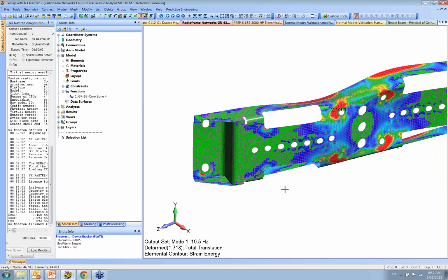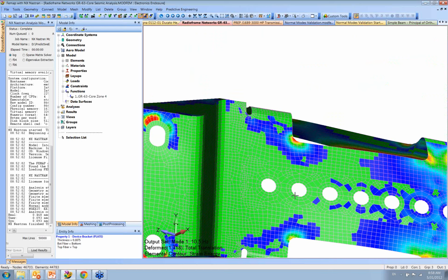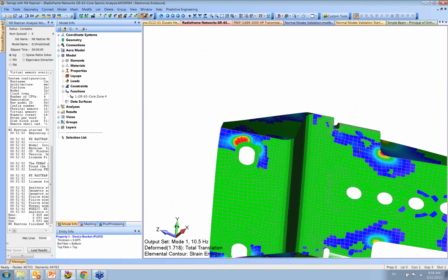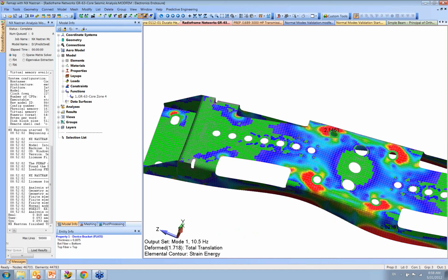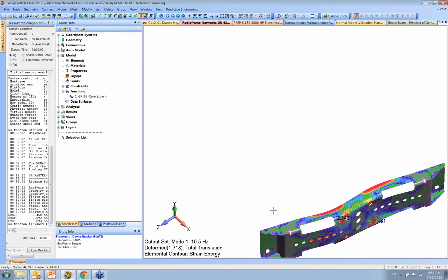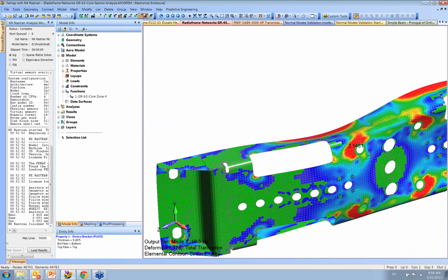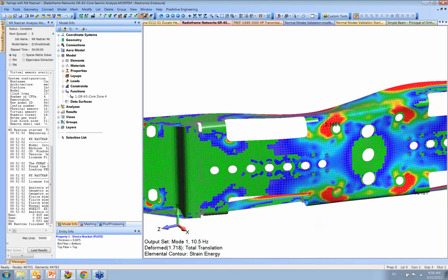This bracket went through several iterations of reinforcement, and we were looking for high strain energy density. These blue regions here are telling you the strain energy is so low it fell off the cliff. They just don't report the values because they're near zero. Then you get these high regions around here, and if you wanted to take it to the next level, you would reinforce this region right around the clamp or make it thicker through here. But we reached our target, so we just stopped.